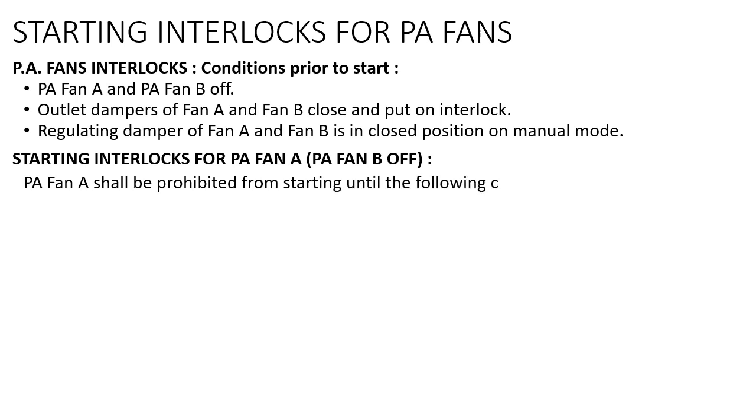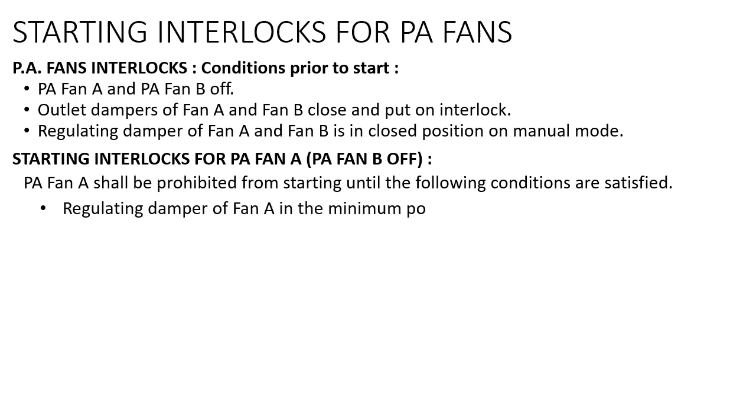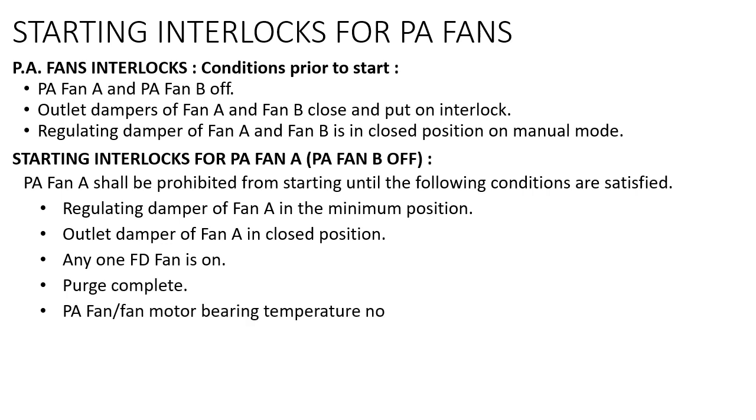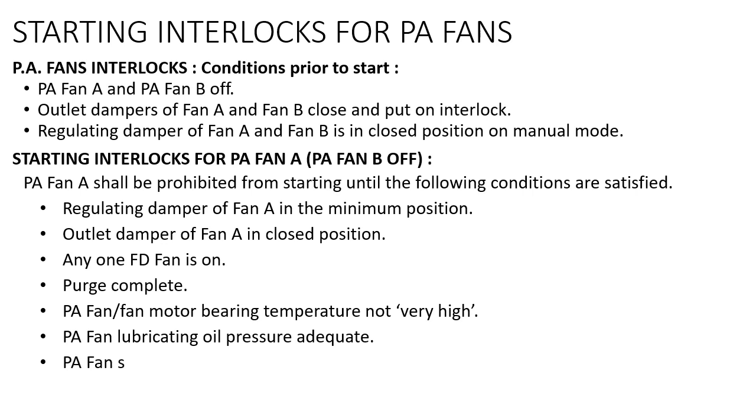Now the starting interlocks for PA fan A, when PA fan B is off and we are starting PA fan A. PA fan A shall be prohibited from starting until the following conditions are satisfied. Condition number 1 is the regulating damper of PA fan A is in minimum position, the outlet damper of fan A is in closed position, then any one of the FD fans should be on. Purge complete must be there from the FSSS.